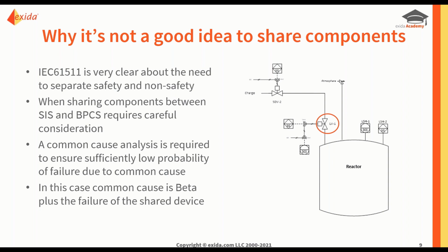It doesn't necessarily preclude using shared devices, but as you can see in this example with our LV1, if that's also going to be driven by the SIS and the BPCS, if it is not a certified device, then its reliability may not be as good as required for a certified device.